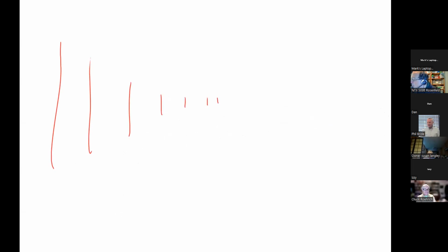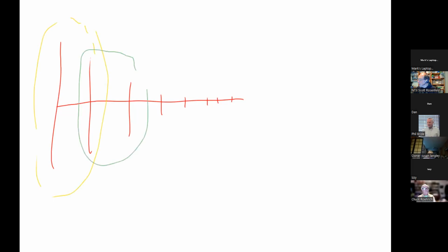And the way that this works is that these antenna elements are logarithmically related, so that on any one given frequency, only two of the elements are actually in play. So on another one, it would be like these two. On another frequency, it would be only those two. And what that allows you to do is have a very, very wide bandwidth. So this could be used from like 100 to 1,000 megahertz successfully, but with low gain. So very wide bandwidth and very low gain.